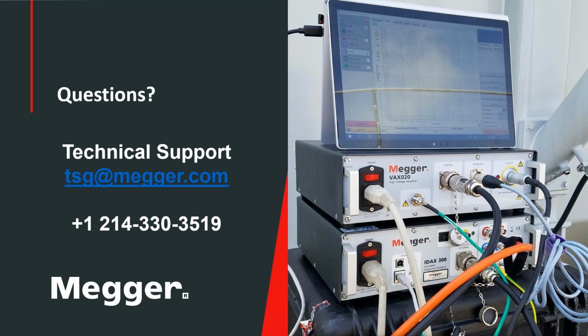And of course, you can do a hot collar test as well on lower voltage, right? Typically, you try to do your hot collar test at 10 kV, depending on the rated voltage of the bushing, but you can do 2 kV as well and have a reference value. In this case, you're not looking into power factor values, you're looking into current and watt losses. So that is the answer.